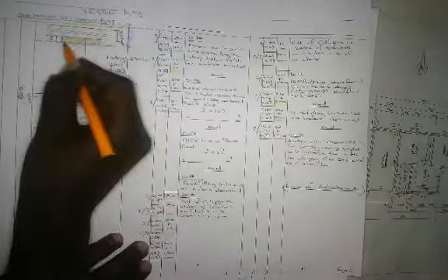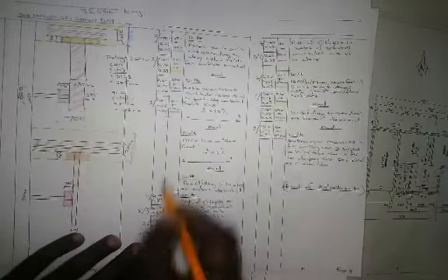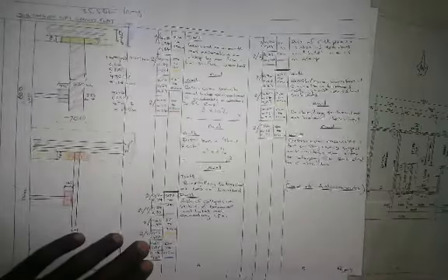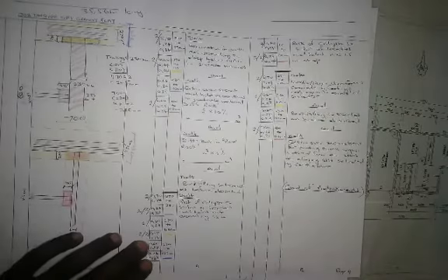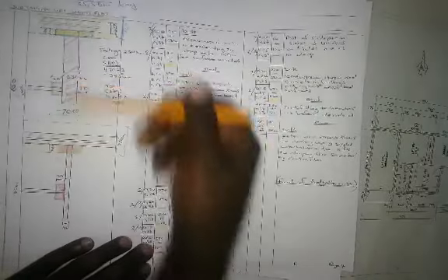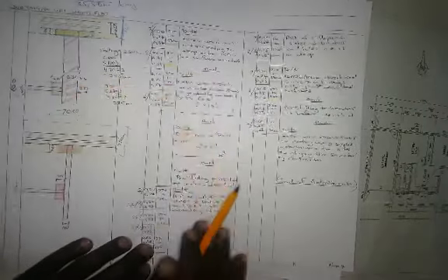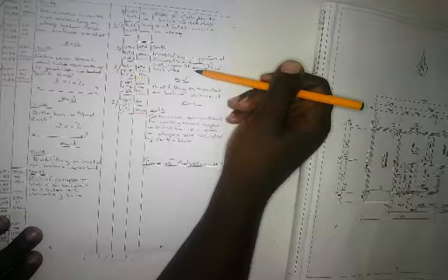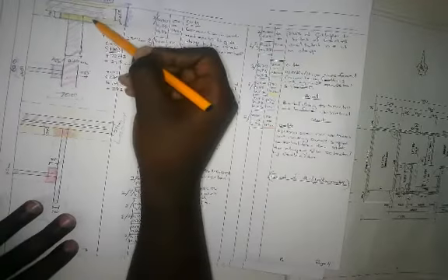You're going to deduct this risk of collapse that is over here, because it's already been measured under another item. So that's why you're going to have 0.7, which is the width of this trench where you have deducted, times 0.84, which is the depth of your trench. I hope that's clear.